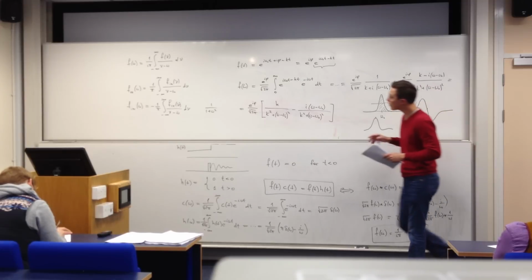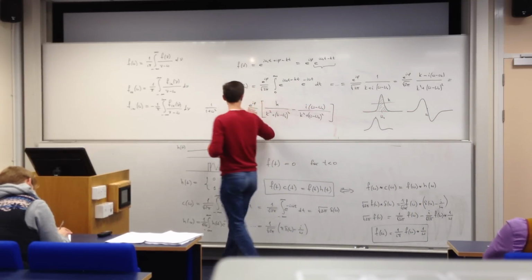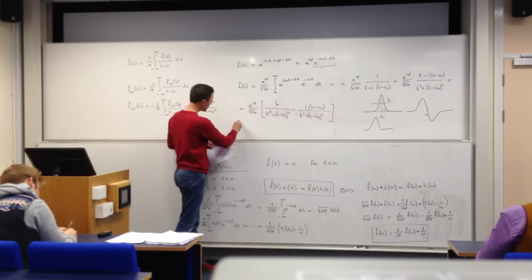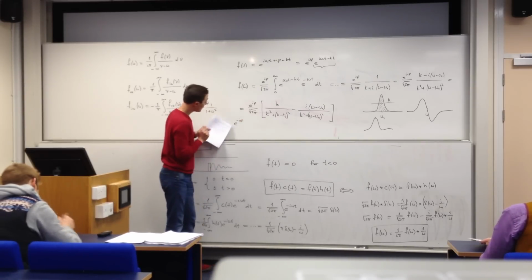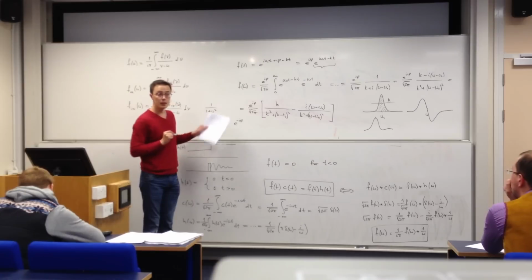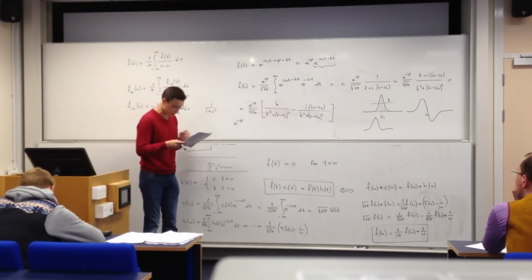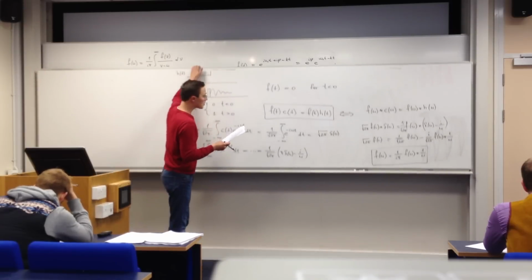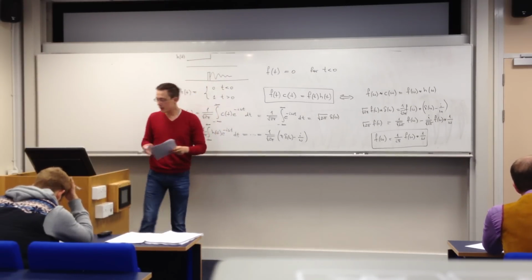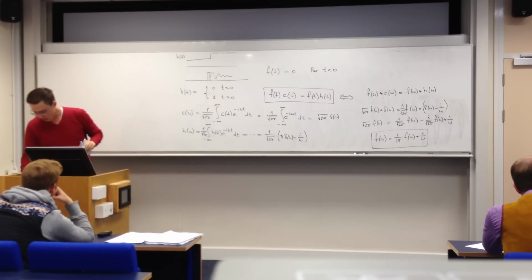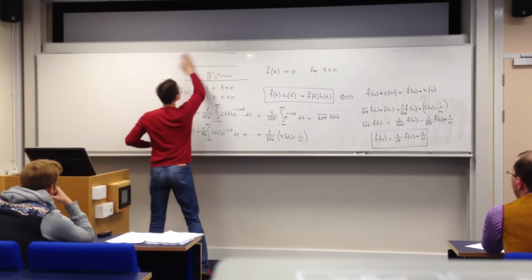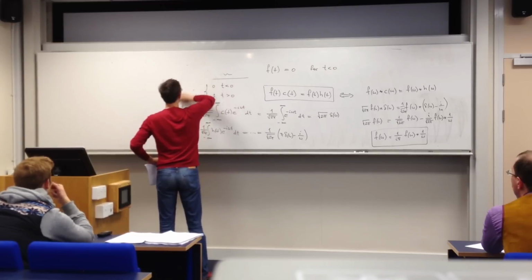And let's say we have detected a signal with a phase e to the i phi. So we'll now need to find phi and multiply by e to the minus i phi, and that would actually phase the spectrum. Right. The way it's done is, you know, multiplication by a complex number is equivalent to rotation in the complex plane. So we simply need to find the backwards rotation.